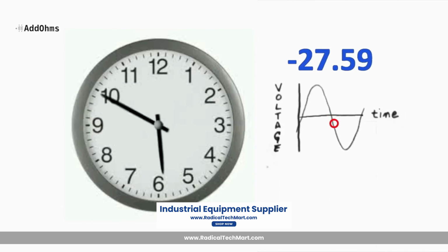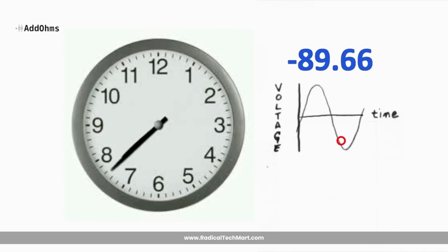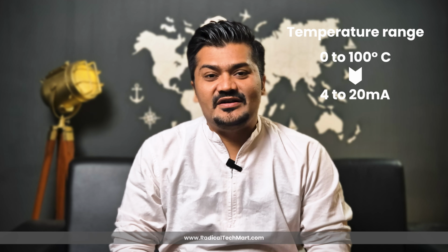Analog signals are continuous signals that can have an infinite number of values within a specific range. Let's take one example. If you are measuring temperature from a temperature transmitter and your minimum and maximum value is 0 to 100, then its output signal from 4 to 20 milliampere can show a continuous signal that can have an infinite number of values within 0 to 100 degrees Celsius. Another example you can take is a pressure transmitter providing a 4 to 20 milliampere signal.